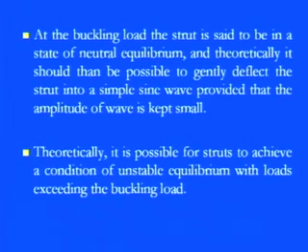So now you see here, once we know that the buckling is there, and due to buckling, whatever layers are there of this particular strut are now under deflection or deformation, and they are forming, as per the kind of load. So generally we are saying that this strut is now divided into a sinusoidal form, because this is a periodic phenomenon.